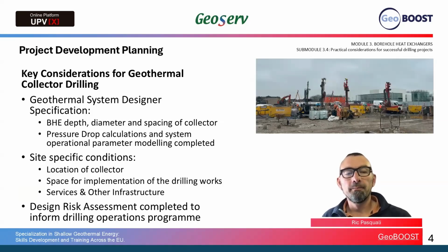They will have also carried out simulations to determine that the installation of the geothermal probes and the borehole heat exchangers is correct, that the diameter has been selected based on acceptable pressure drop calculations, and that these calculations have also identified the operational parameters of the final system.